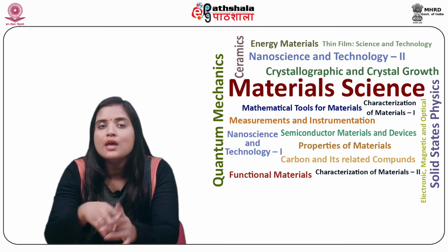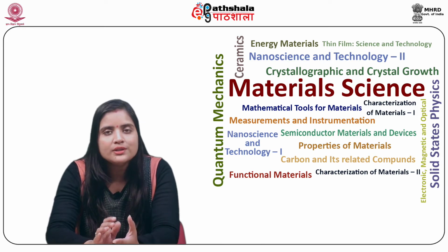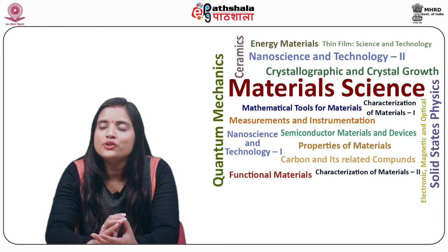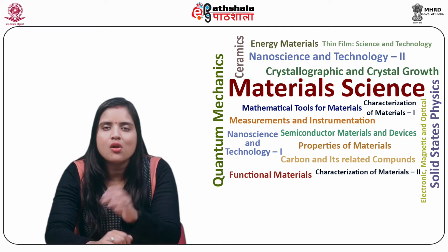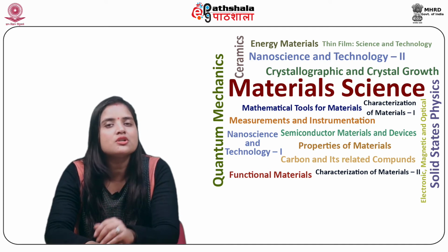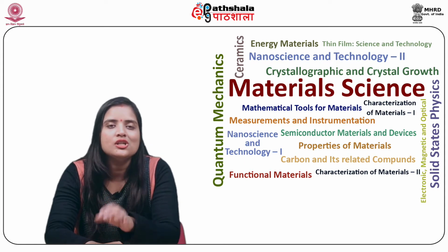The shell is partially filled with balls. The balls form the grinding medium of the ball mill. These balls are usually made of steel, ceramic, flint pebbles, or hard rubber. The inner wall of the shell generally contains a coating of abrasion-resistant material, for example, manganese steel or rubber.